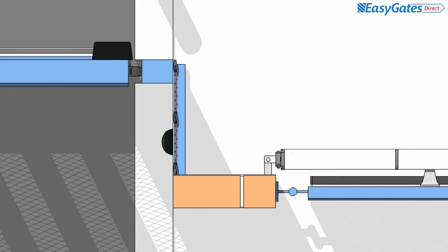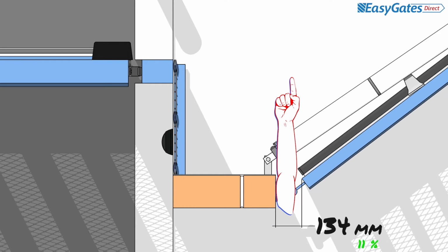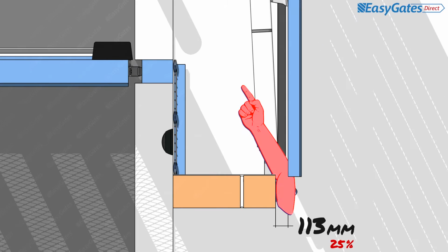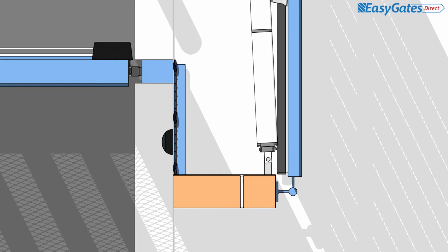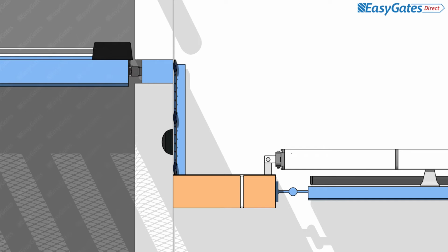The Code of Practice defines that where the hinge gap in a swing or bifold gate varies by more than 20% and or is over 100 mm, then this is considered to be a hazard. Please note, all other hazard areas of the swing gate, the hinges, sweep obstructions and etc. must be assessed separately and designed out or eliminated where possible.